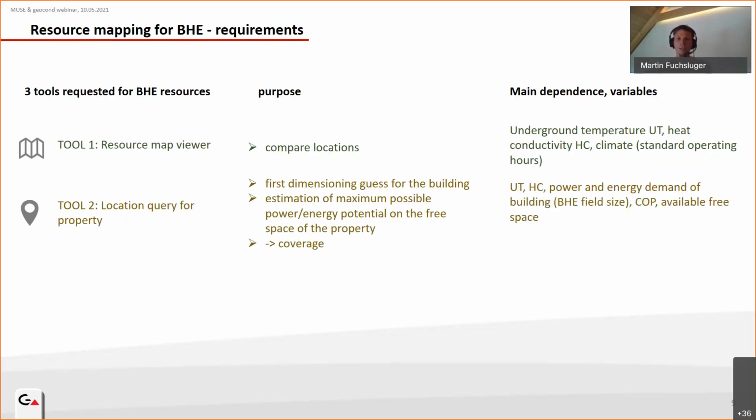And the main dependencies of this tool are, of course, the power demand of the building, which dimensions the field size and the influence of the field, and next to that the underground temperature, heat conductivity, and also the seasonal performance factors, here COP, is important, and the available free space.